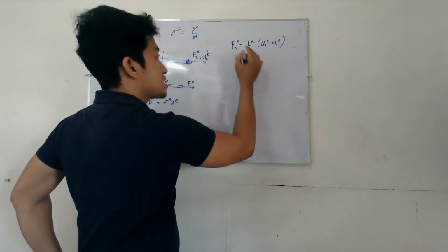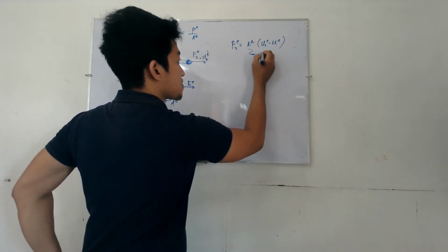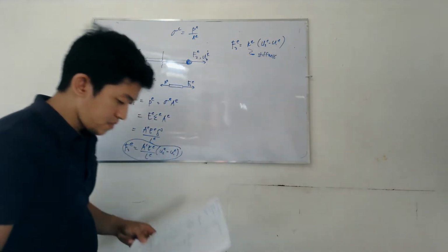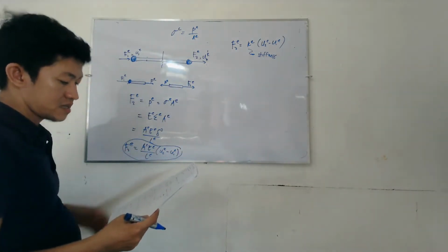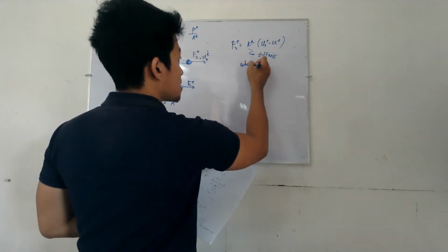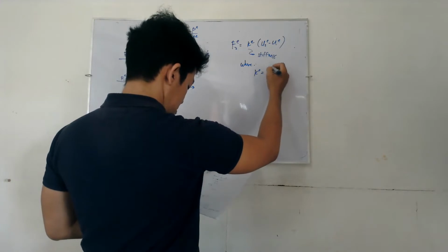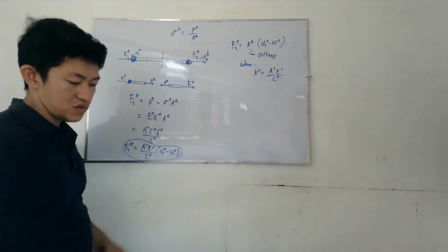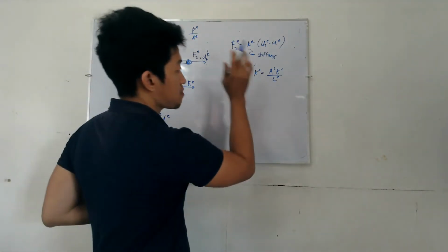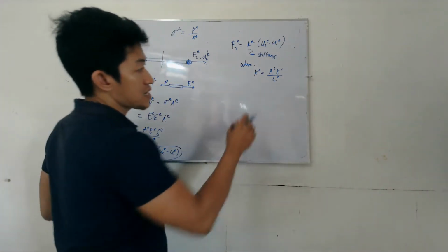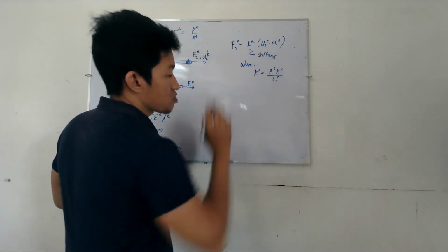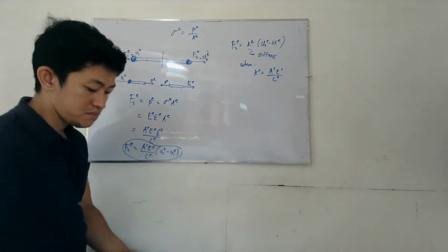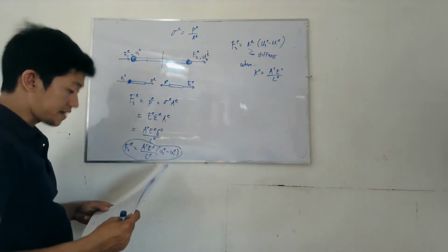So your K is the stiffness of the material, where K is, the stiffness is the same as the stiffness of your springs. To get it, it is just area times the modulus of elasticity over the length. Okay, its unit is Newton per meter.